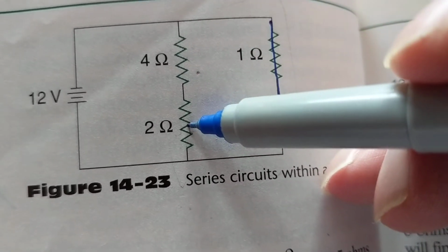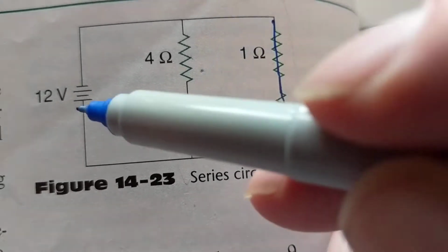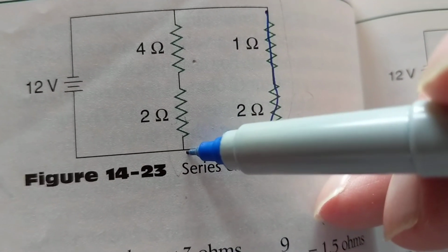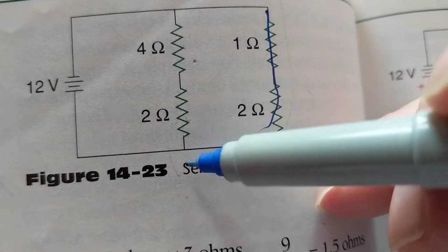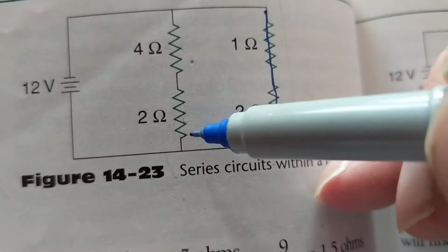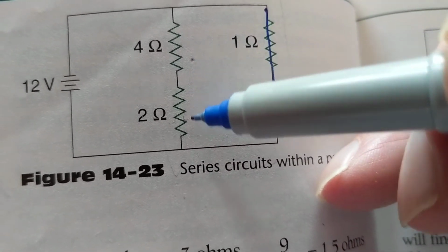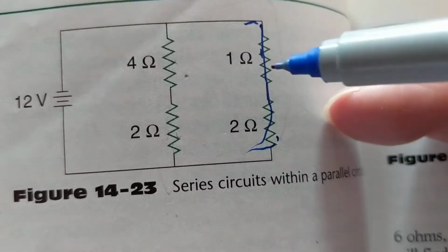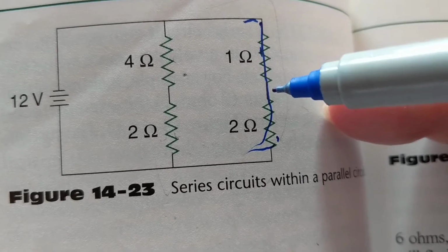Let's say if this one is open, this bulb open, this resistor open. Current comes here and says, okay, I have 2 paths again, but this one is open. I'm not going to take this one. I can't go there. It's open. It's like a drawbridge that's open. You can't cross over it. Current can flow in this one. Why? This is a complete path.